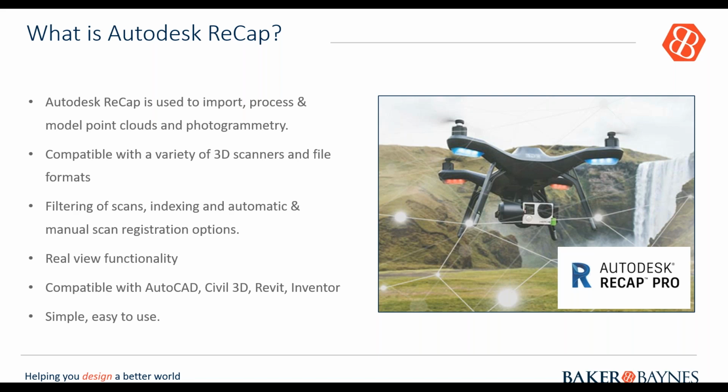The great thing with ReCap is that it is very compatible with a variety of 3D scanners. So whatever you are using, it more or less integrates with that file format, okay? And it has been used with all your famous scanners such as Topcon and so on. So you can use it across the board. The main purpose of it is that it's a dedicated tool for your point clouds and your photogrammetry. And in terms of point clouds, it helps you to filter your scans, index them, and of course, it gives you the option to automatically or manually register scans.